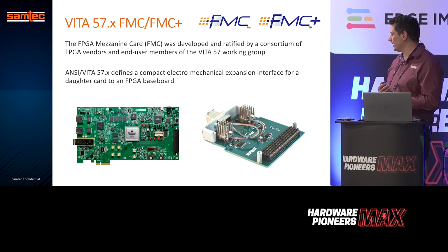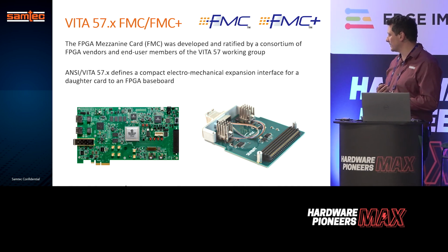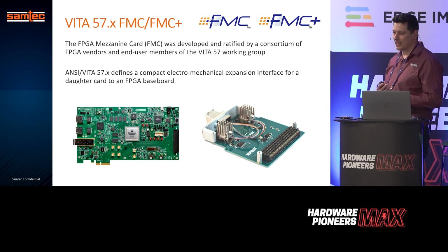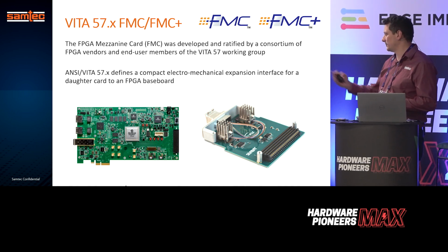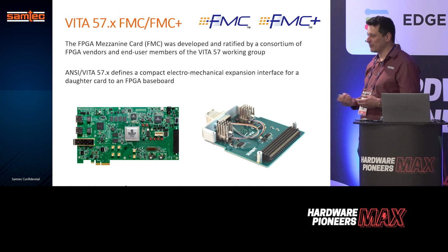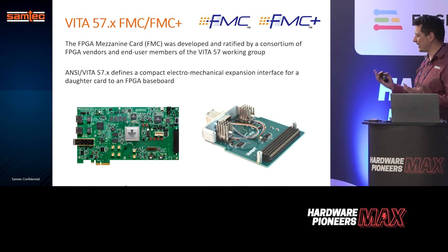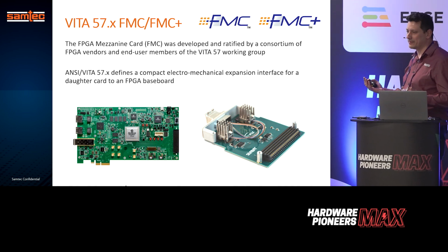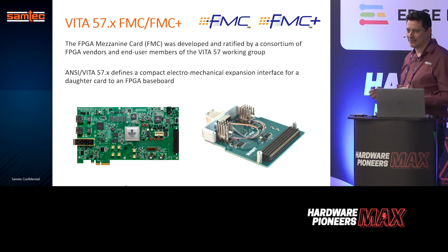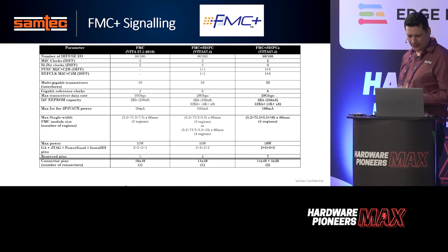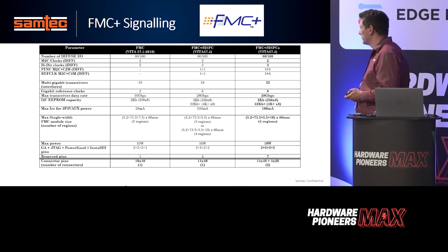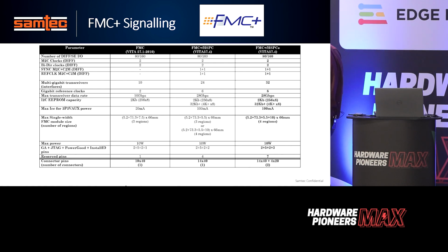But we see a big interest from customers on designing their own FMC cards on their own FPGA carrier cards. So obviously you will not use an evaluation kit on production, but at the same time you will design a similar carrier card that will offer the functionality that you are looking for. So when we look at the FMC, there was an evolution initially released in 2010 by the VITA organization group.